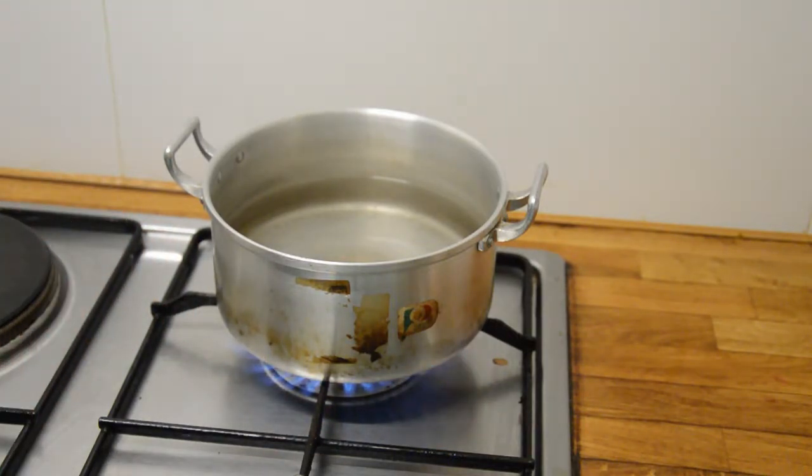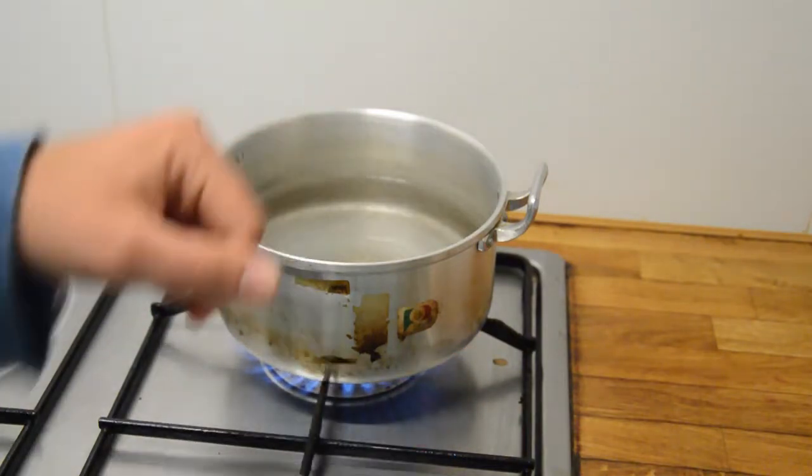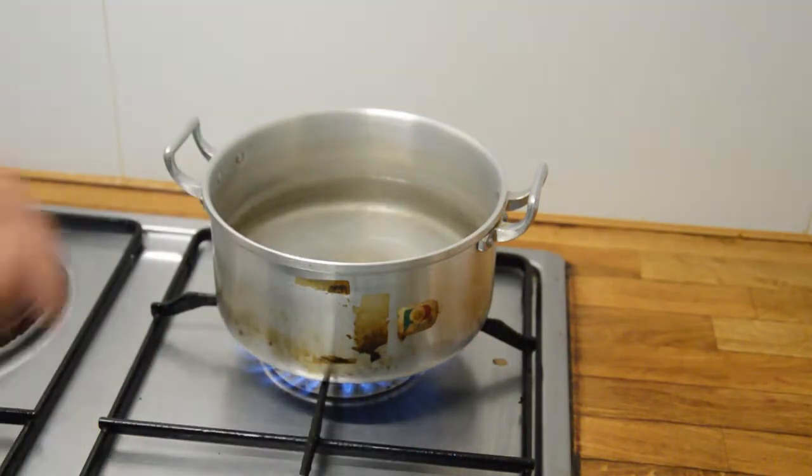Second loss is evaporation. Now that the temperature is still low, it's not very important, but when the temperature rises around 70, 80, 90 degrees, when it's still not boiling but it's almost there, then it's gonna be a huge loss. The third loss can be considered a loss by conduction, which can happen on the sides. Some of the heat will go from the water to the metal and from the metal to the air, but it's a very small loss, in my opinion, compared to the loss from the flame and from the evaporation.